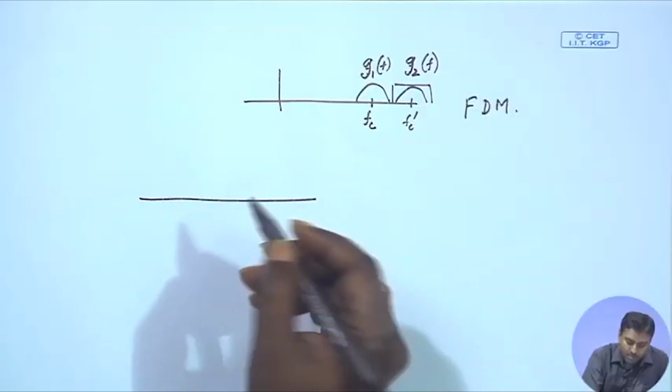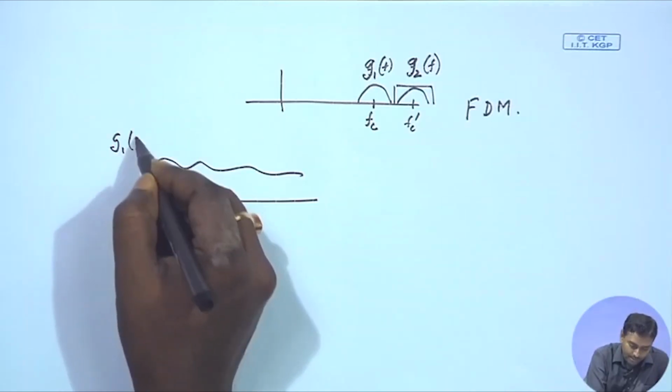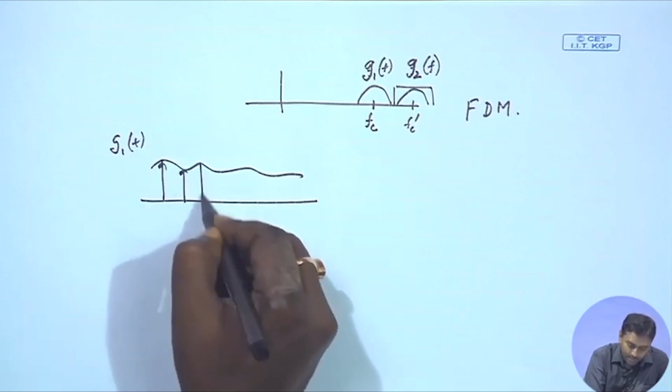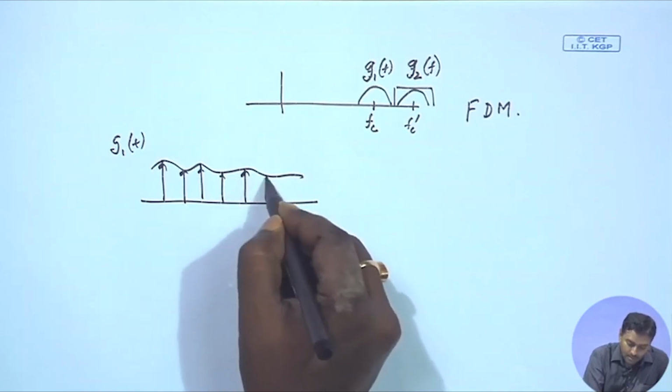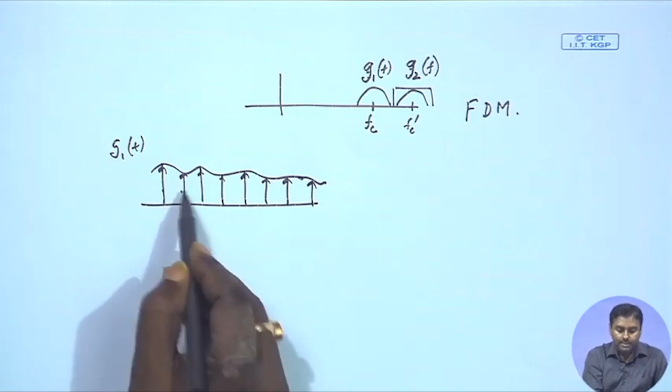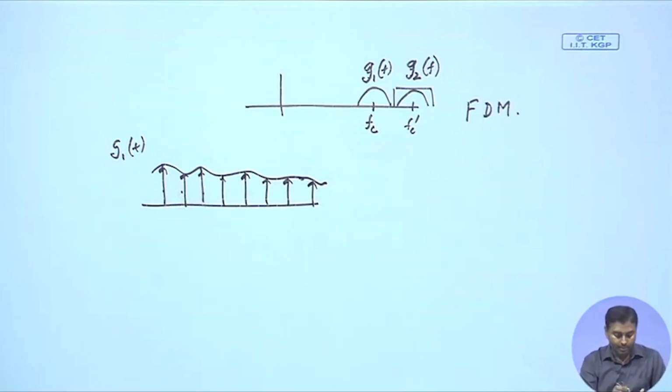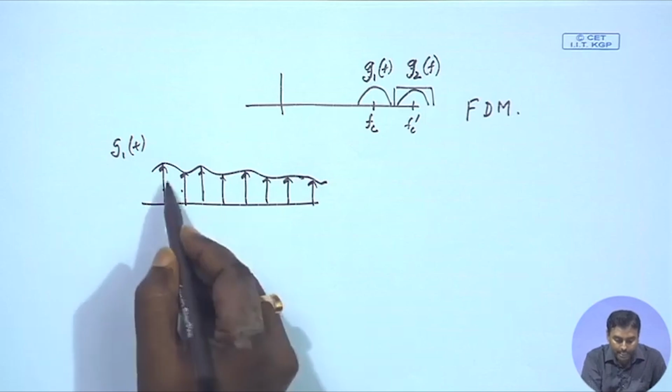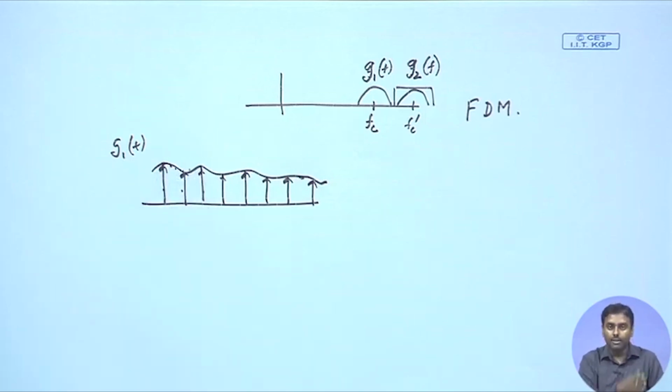Now, by the sampling theorem, we have another opportunity. Suppose I have a signal, let us say G1(t). I put a few samples to represent it. If you see it in the time domain, we have already proven through the interpolation theorem that these samples are the sole representative of the entire signal. So, I do not need the description of this signal for the entire duration of time. I can just take those few samples; a discrete time description is good enough to represent the whole signal.